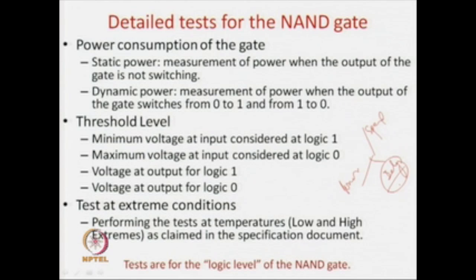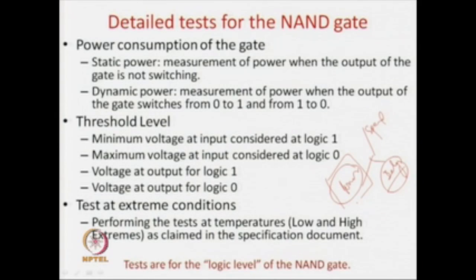Another very important constraint is the power constraint, which is coming into prominence nowadays because we are using a lot of handheld devices like mobile phones and laptops. Many times we say that our processor is working at so much frequency, its speed is so much, and at the same time we also say what the power of the circuit is. Sorry, delay and speed are the same thing; actually I meant area. We will come to area afterwards, that is, the area taken by your circuit. So the 3 parameters of design are area, delay and power.